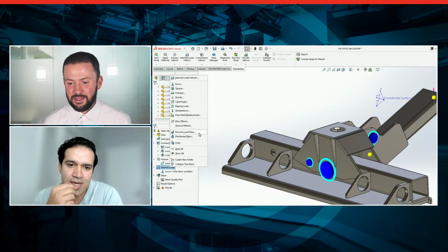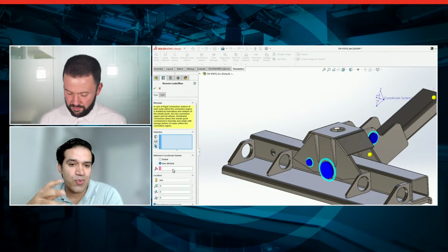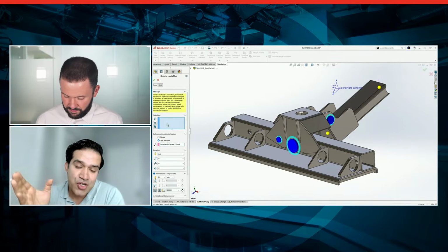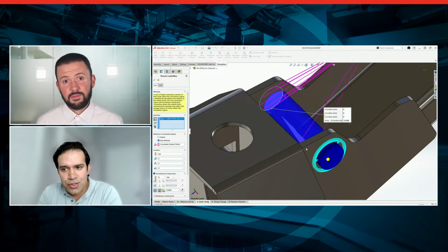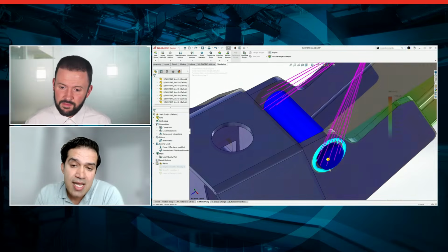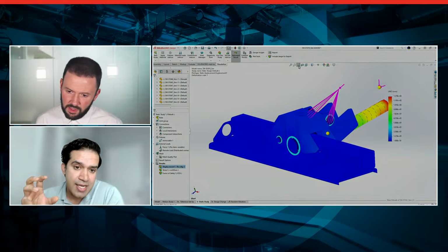That was a really good enhancement, man. The reason behind it is I work a lot with shells, and anytime I'm running these analyses with a shell, I couldn't really use the edge of the shell to set up a remote load mass. But now in 2026, if I define a shell, I have the ability to directly add that load onto the shell edge itself.